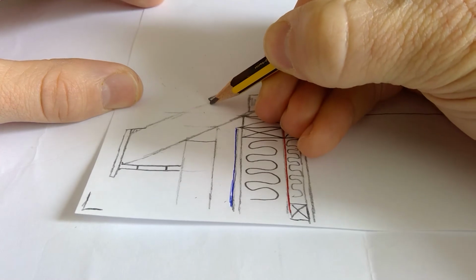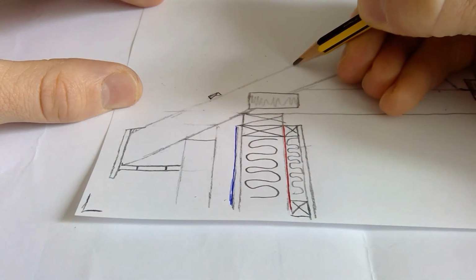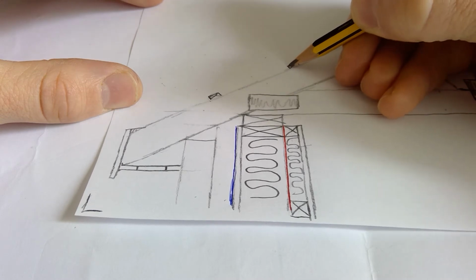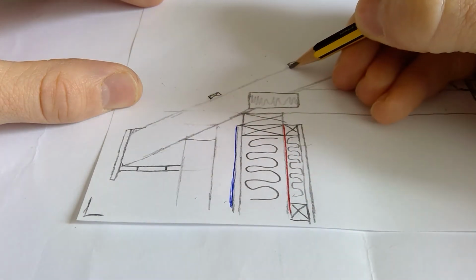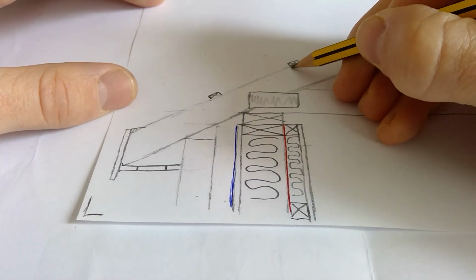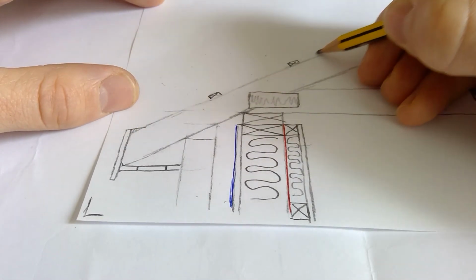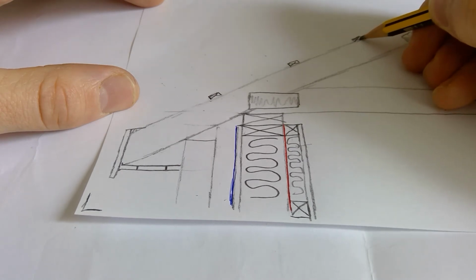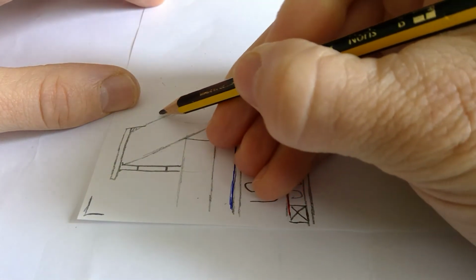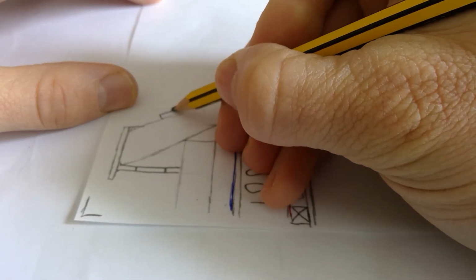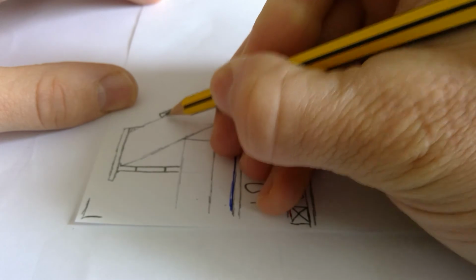From the front of that batten, I measure on 35 again, and I go up 50 by 35. So here to here is 35, and then on 50. One more, it asks for 3 courses of slates. Here on 35, and then move on 50 from there. This very front one, there needs to be 3 slates overlapping here, so you put a batten in between the middle there. 50 by 35.